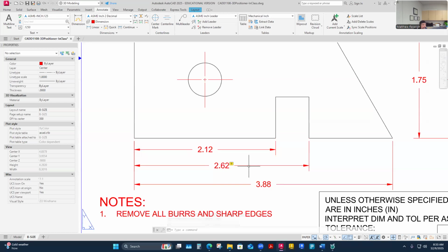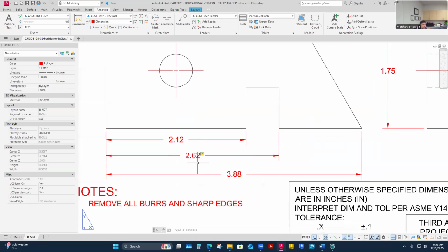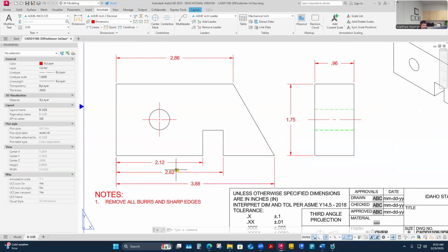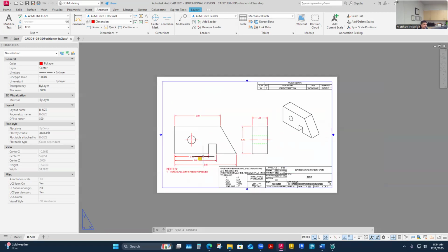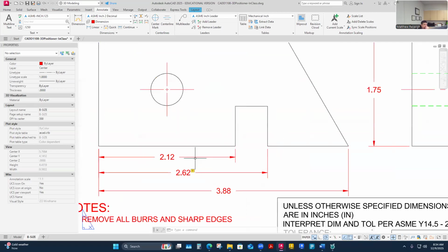My advice is don't stress too much, because it's kind of like the dimensions on your other drawings. They're not going to be super even. Previous to 2D drafting, you always would have to move your dimensions a little bit. So I say if I get 90% of them, I'm in good shape. But you'll know you have a problem child here. Like I said, I'll spend a little bit of time to see if a quick reassociation or a grip here or there will help me. And if not, I just move on, because I'm not going to spend forever trying to fix it. I feel like it's probably operator error, but I blame the program on this one.